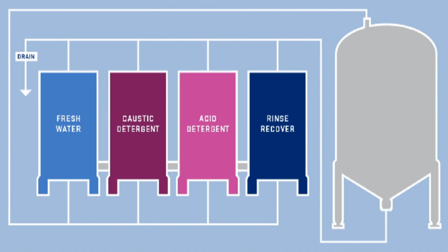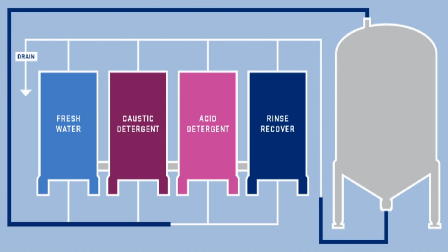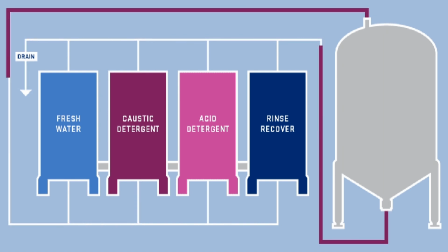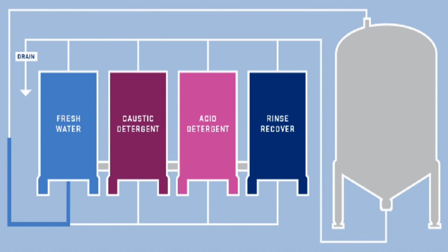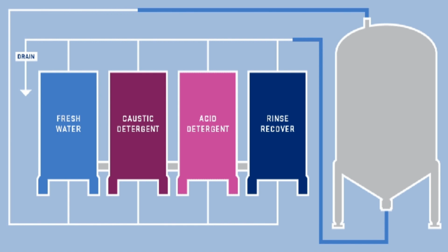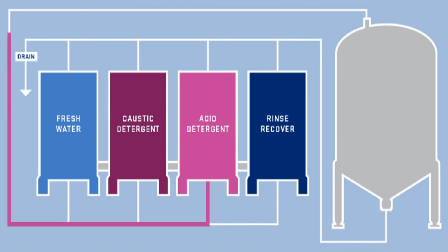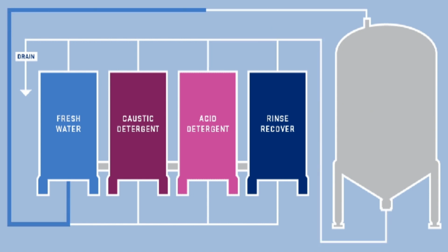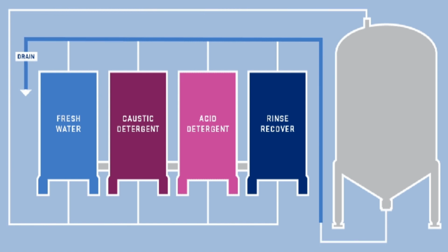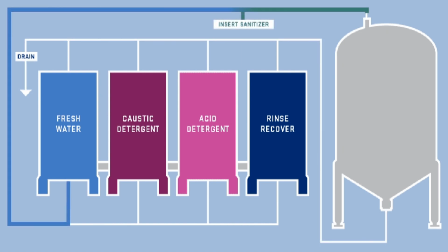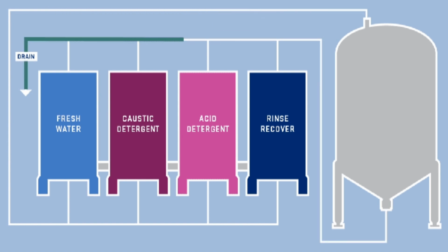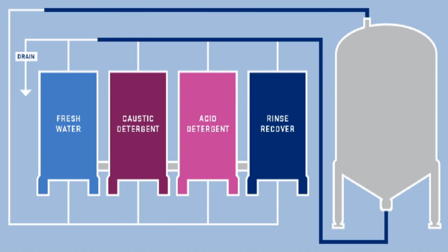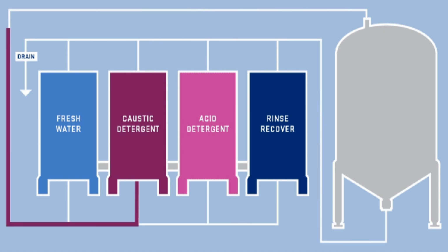tanks, and more. CIP systems have an important role in processing because of the need of keeping process components clean and sanitary. Without the use of a CIP system, one would have to manually disassemble the process to clean it. The CIP system I designed consists of 3 chemical tanks: a rinse tank that runs between each cycle, a caustic tank that contains caustic chemicals to soften fat, and an acid tank that contains an acid chemical to dissolve and remove inorganic residues and bacteria.